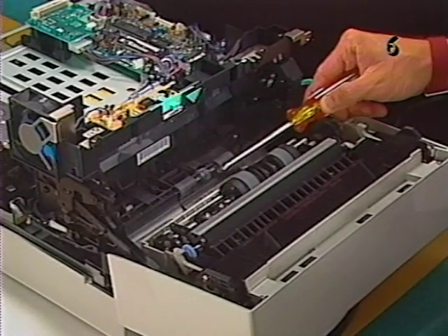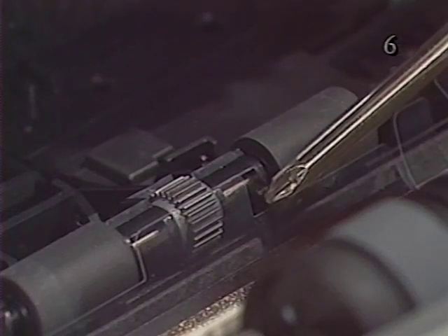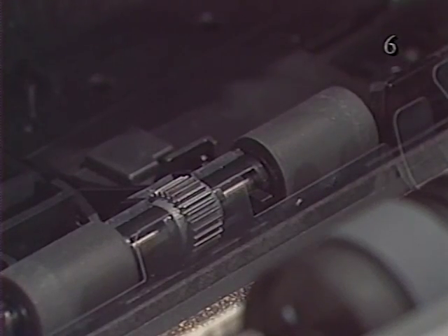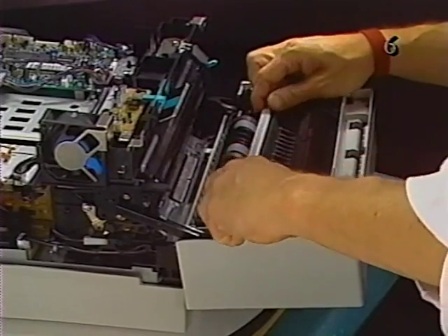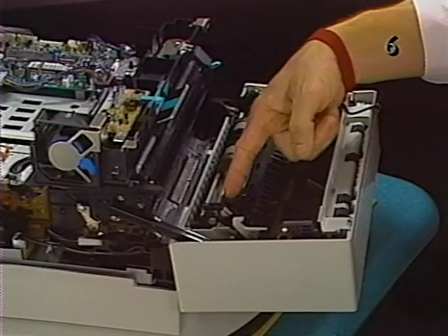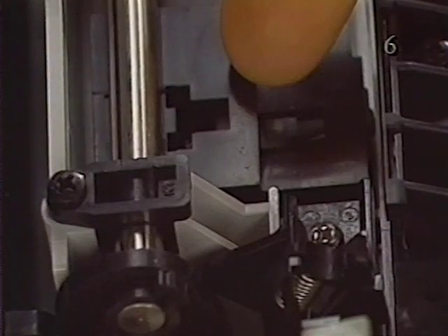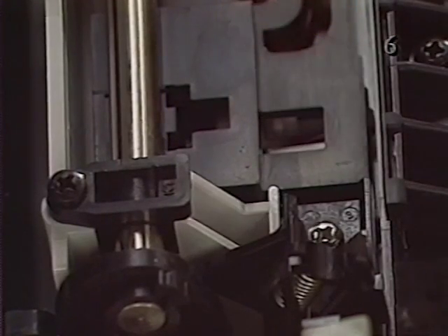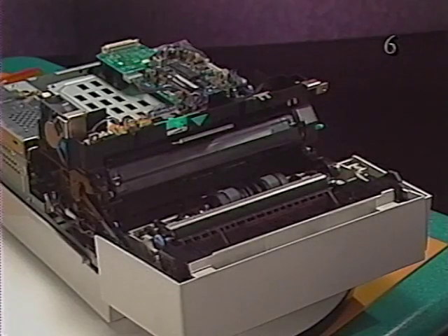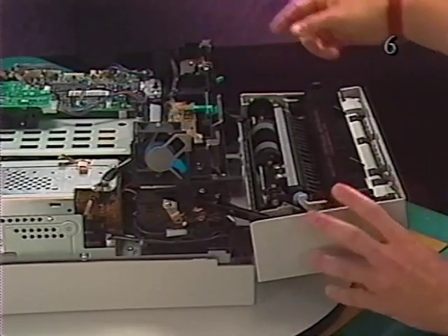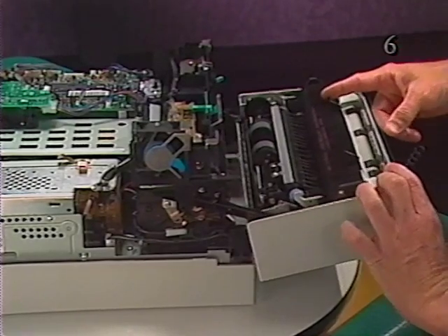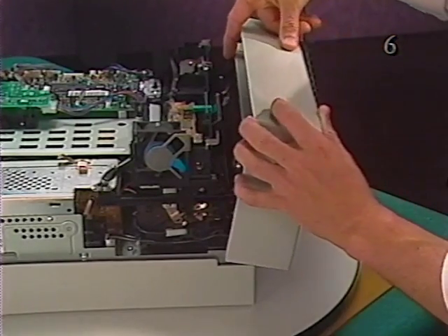Sensor PS13. It detects if paper is in the pickup unit. Sensor PS502 detects if the face-up tray assembly is open. And finally, sensor PS12. It detects if a sheet of paper exits the fuser assembly. Now, if this sensor is not activated in a set period of time, a paper jam is determined to exist.